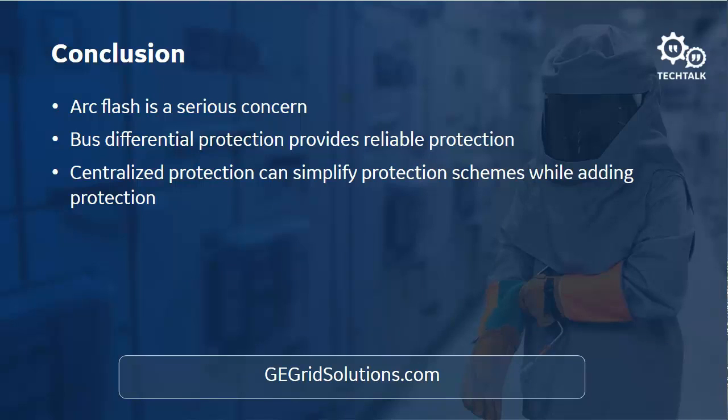If you're doing something new where you can add that in, then it would make a lot of sense to do the centralized protection. If it's existing switchgear, then the standalone protection relay with arc flash is a valid option. We also do have things where you can add arc flash protection in, say, a transformer protection relay, and then take the arc flash sensors from that relay and route them, and if they see something, you trip the main.